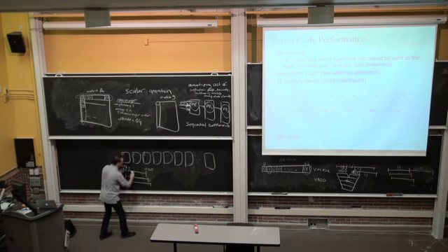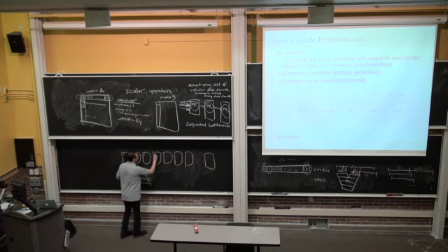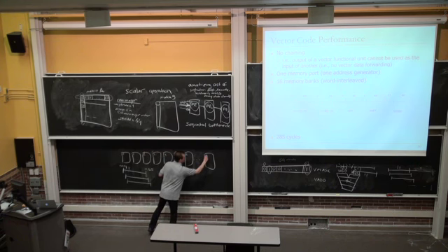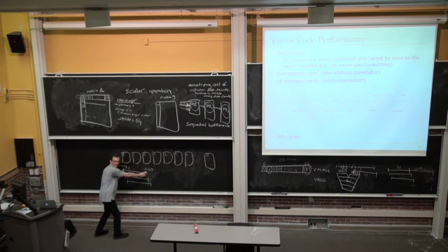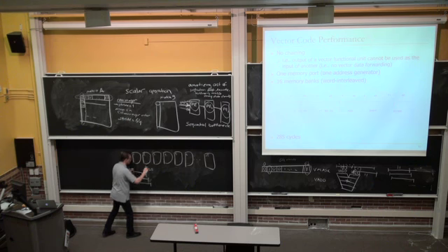So if you think about this, the next access, you can start in cycle 3, next access 4, 5, 6. And the 16th element is also here. You can start in the 16th cycle because this bank is already done servicing the first one. Make sense? That's why what I drew was the first element takes 11 cycles, and then each consecutive cycle you can actually get one element per cycle from memory because you already pipelined, if you will, you've already accessed different banks.